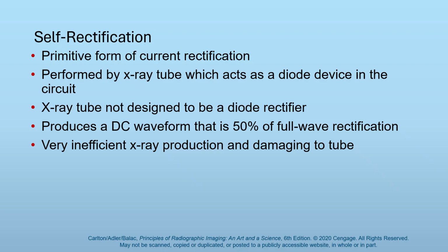The X-ray tube, and that's because the X-ray tube is a specialization of a Crookes tube. It's a re-engineered, souped-up Crookes tube designed to make X-rays, not necessarily create an open core transformer at the cathode filament. And so a self-rectified tube is not a thing. We know better now. That's just going to burn up your X-ray tube. So it's not really a thing. Theoretically, though, it did work for a little while, but you would keep having to replace your X-ray tubes because you always burned out your filaments.